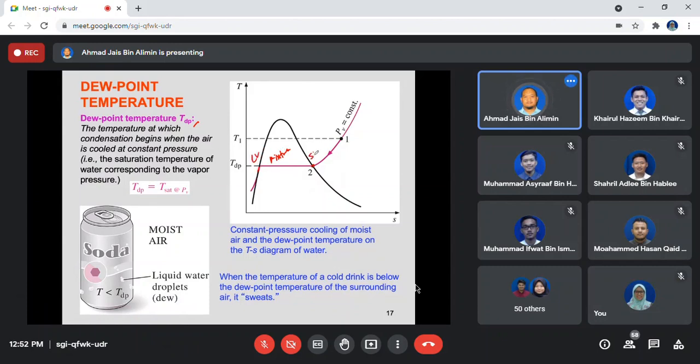The other side is superheated. So at this particular point, you maybe have 99% existing as water vapor, in the table. And maybe you have only 0.1%, or 1%, present as liquid. The moment you touch this temperature, liquid appears, and that is what we call the dew point temperature.